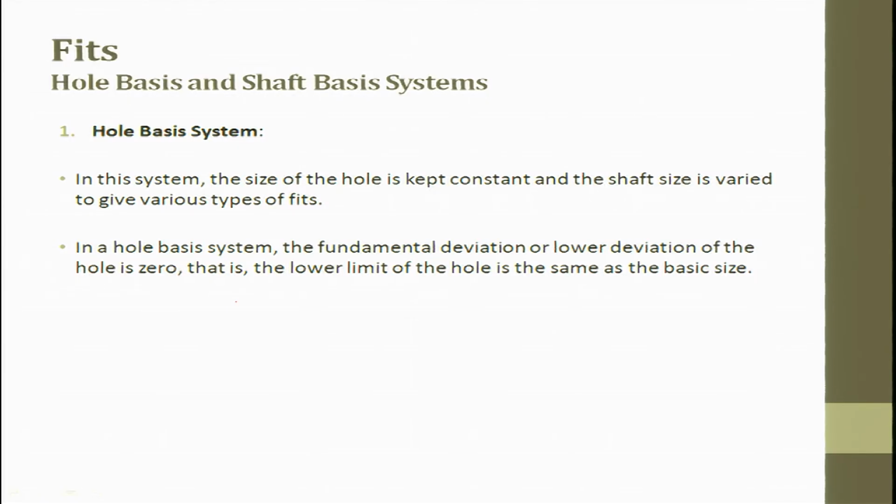What is the hole based system? In this system, the size of the hole is kept constant and the shaft size is varied to give various types of fit. In the hole based system, we always use a capital letter for representation. So in this system the size of the hole is kept constant and the shaft size is varied to give various types of fit.